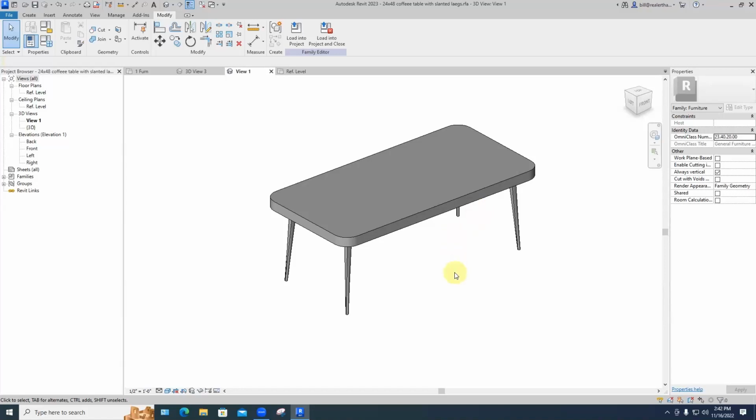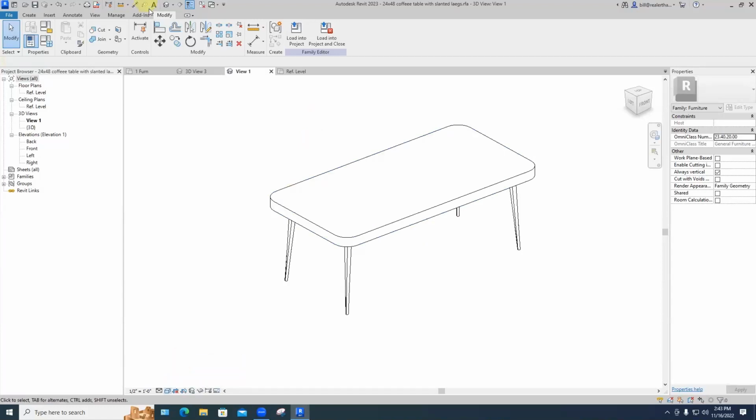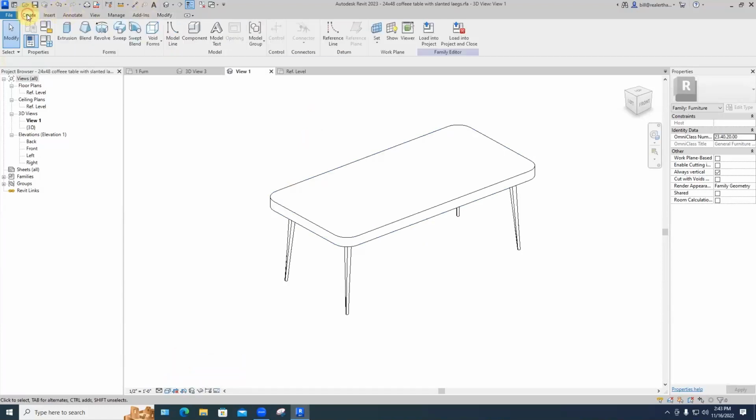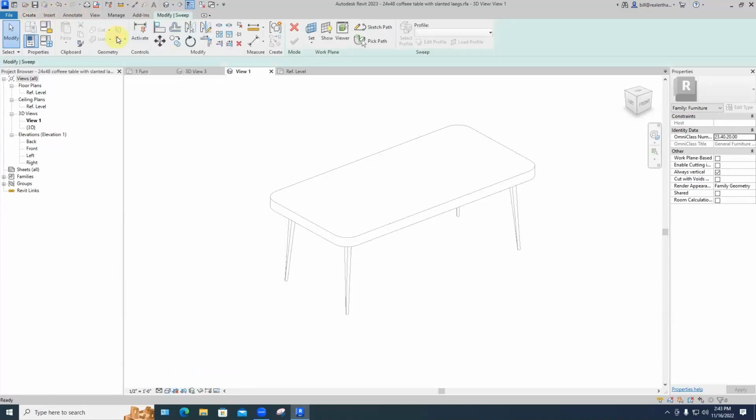A difference in how we make this compared to last time. Previously, we had just drawn a line on the floor for the custom countertop. Here, to define our path, we're going to pick these 3D edges and tell it to draw it there. So it'll be like attached to the edges of the table wherever it goes. So I'm going to go back to, I guess, a hidden line here just for fun. I'm going to create a sweep.